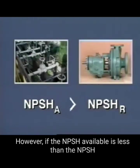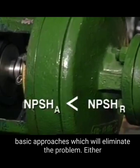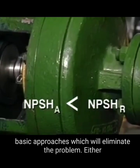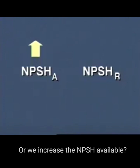However, if the NPSH available is less than the NPSH required, true cavitation occurs, and there are only two basic approaches which will eliminate the problem. Either we decrease the NPSH required, or we increase the NPSH available.